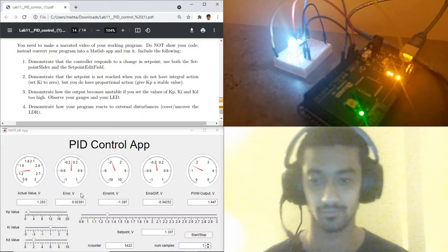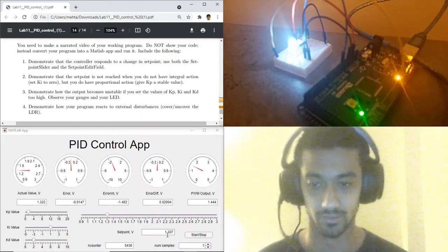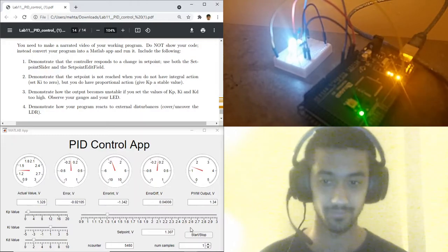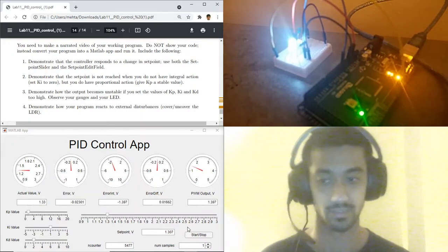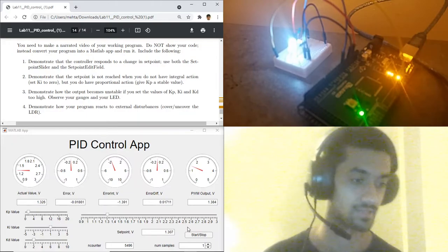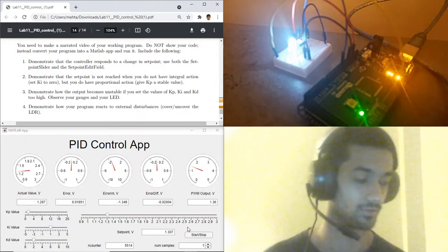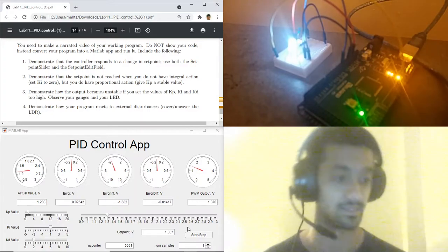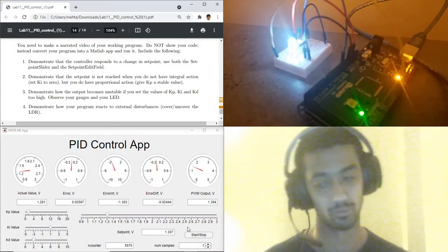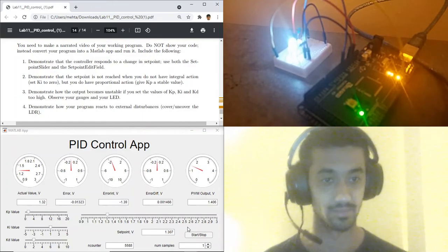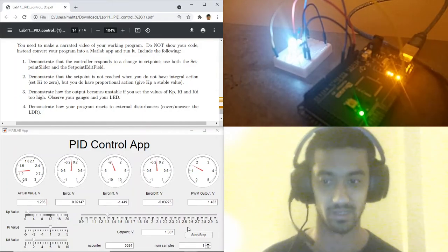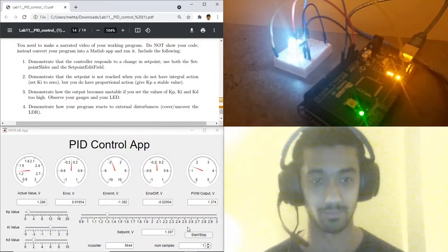Our set point value ranges from about 0.9 to 3, and that happens through the calibration that we did in the beginning, where we first set the pulse width modulation to 5 so that we get its max value, and the lower calibration where we set the PWM to 0 to the LED, so that we see what the range of output values the set points can possibly be.